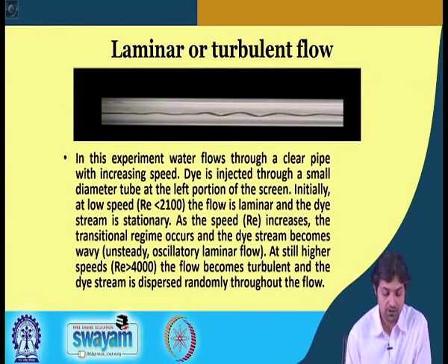Alright. So you see, we have read in the chapter on laminar and turbulent flow that one important property of turbulence is dispersion and mixing. In this particular video, you will see that the dye stream is dispersed in all directions, clearly indicating that what we had learnt in the laminar and turbulent fluid flow chapter in this course of hydraulic engineering was correct. We can verify that experimentally and by visual investigation.